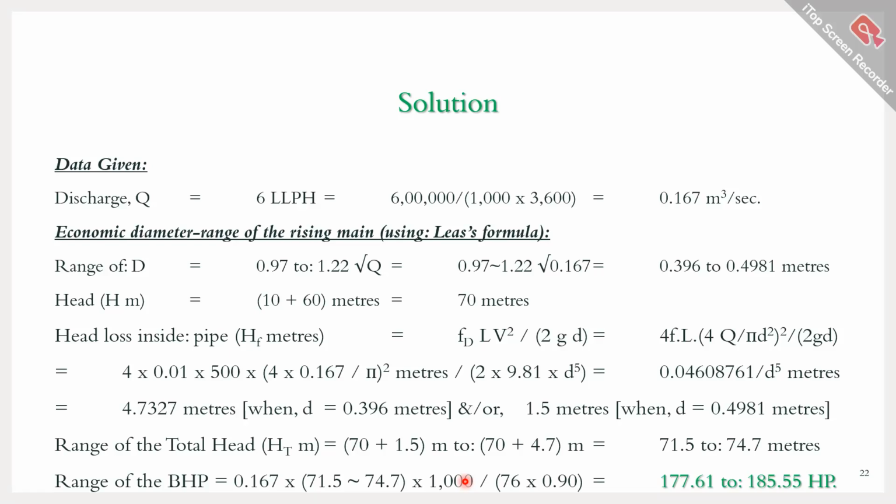Okay. So this H is there, Q into rho. These are these two terminologies. Q means this volumetric flow rate, Q into H into rho. H you have calculated, rho means the density of the water, which is nothing but 1000 kg per meter cube, or 1 gram per cc. 1 gram per cc means 1000 kg per meter cube in SI unit, because all of the units are in SI unit.